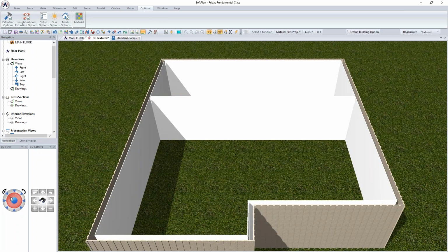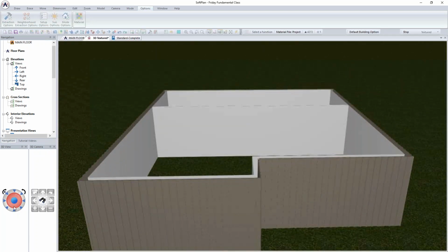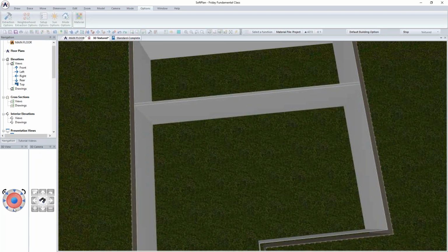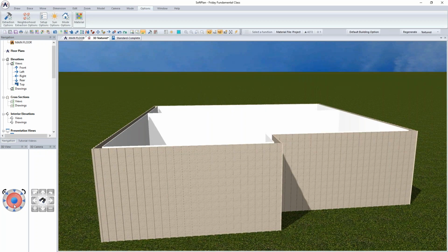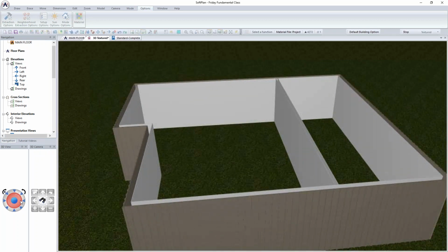This triangle right here is viewing it from the front. Okay, moving to the red circle that you see here, this is going to control the incline of the camera to the focus point. Now the key here is that it takes the current view you have on screen, and basically the bottom of this red circle treats that as the current view. So if I click over here to the right side of that, in other words, you would expect this to rotate at 90 degrees while adjusting the incline, and it does.